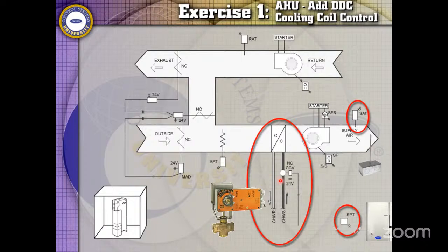There may or may not be a space temperature in this system. Typically, there is not. There's a space temperature on every VAV box, but there very rarely nowadays is one on the air handler. But historically, we had a space temperature on the air handler, and that was for nighttime setback mode. At nighttime, we basically just opened up all the dampers. We ignored the existence of them having controls. And if it got cold in the space, like below 60 degrees, we would energize the heat. Or if it got hot above 80, we'd energize the cooling in the middle of the night, just to kind of temper the building or whatever, right? And then we'd ignore that sensor during the daytime and run 55 degree cooling. But nowadays, we don't typically do that. We just use the DDC system to look and see what the zones happen to be doing.